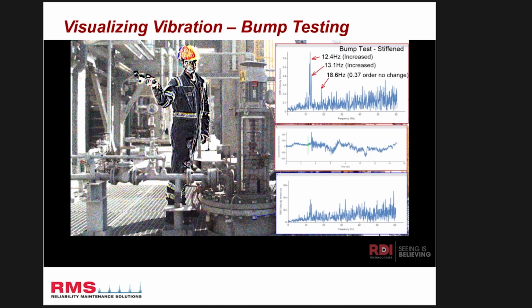I don't know if you've come across bump testing. I know the guys from HD would have. So often is the case where we get a resonance situation, a natural frequency of a system that resonates when it's amplified by a forcing function. So often we have to do a bump test, and what that usually means is we'll add an accelerometer to a motor or a pump, remember an accelerometer with a magnet base, and then we'll use an impacting hammer to impact the structure and look at the resultant response, which allows us to work out the resonant frequencies of the system.